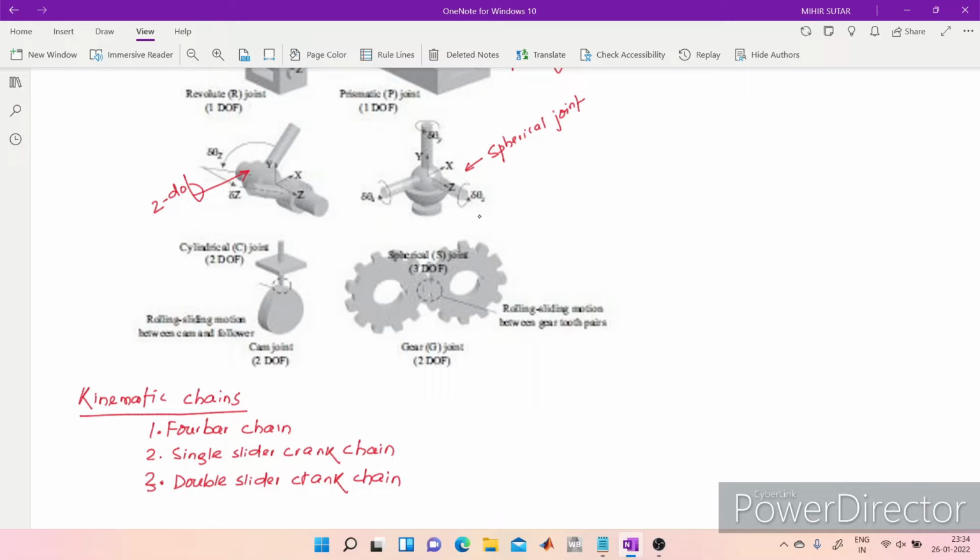Remember, it can be rotated along all the spatial coordinates. For example, if you are going on a bike or a scooty, you might have seen your mirror, and they are fixed in a spherical joint. So a spherical joint has 3 degrees of freedom, remember.